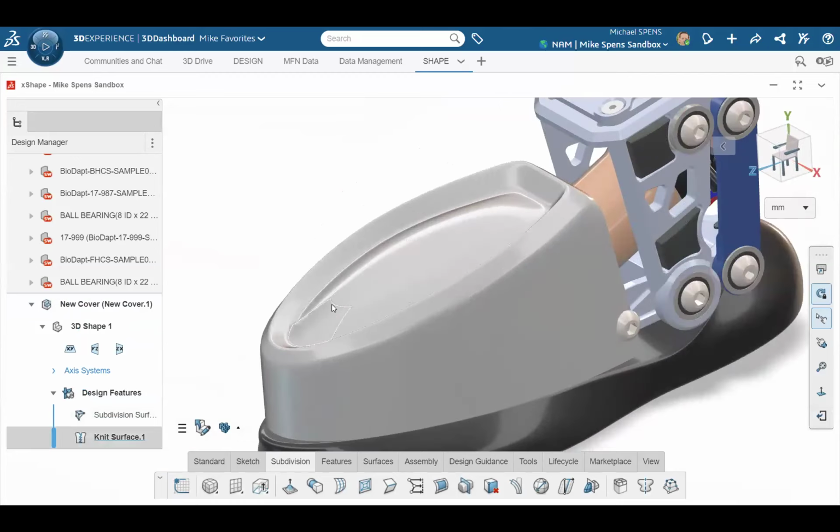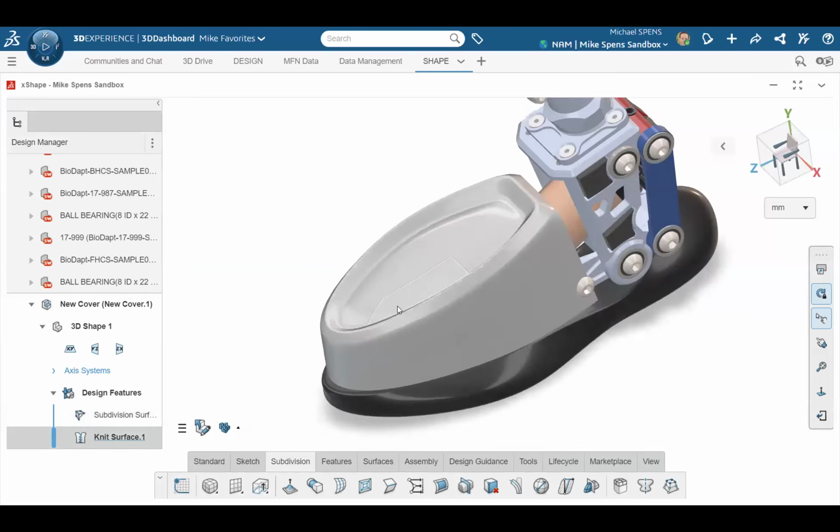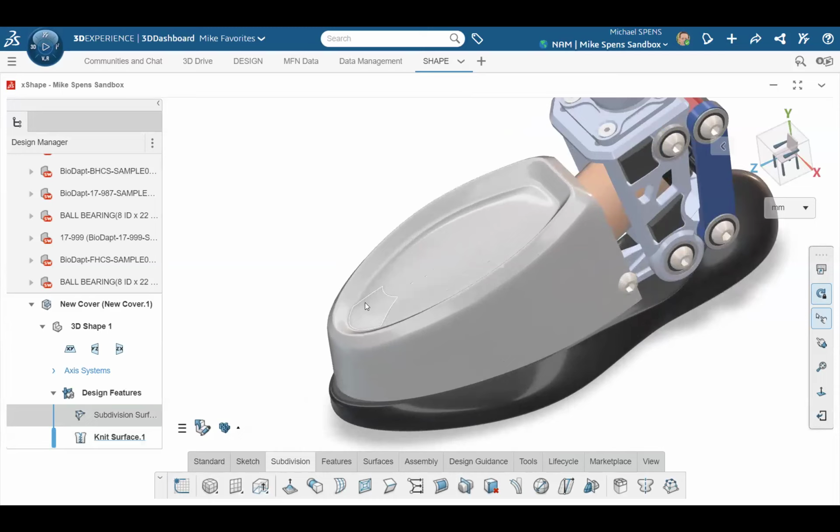So in SolidWorks, if I want to go through the mold generating tools, I can't use this model directly? Yeah, I can. Yep. This is a solid body that you can use inside of SolidWorks to core and cavity a mold and all that. Yep. And shoot out a split line and extend faces and do all the rest of that. Yep, exactly.